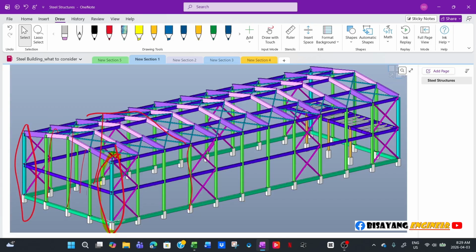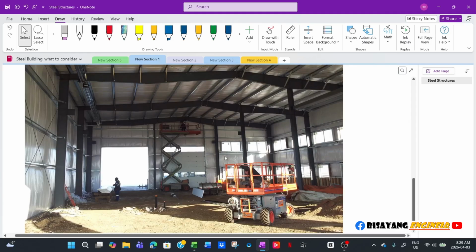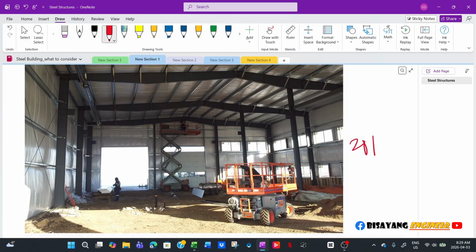I told him the only time I've seen a wide flange, a regular W section, used in a structure like this one was in 2012, in this one here. I told him the most efficient section would be the tapered, non-prismatic section. The first and last time I've seen a pre-engineered building that uses a W section is this one, in 2012.